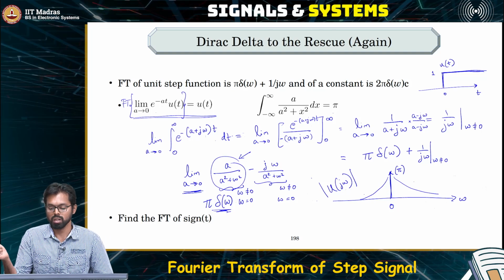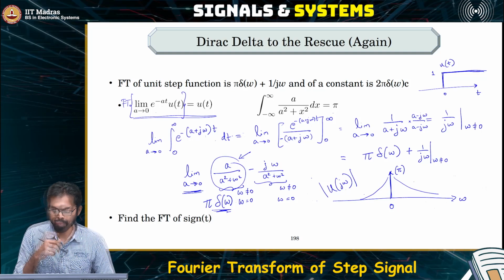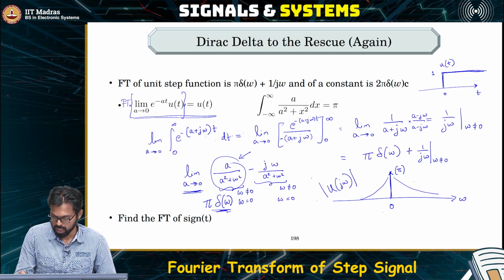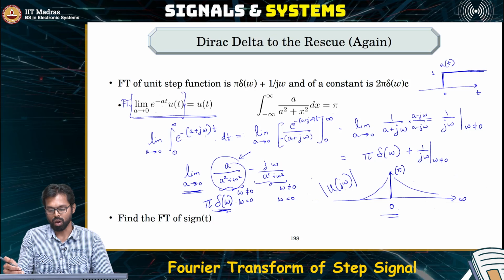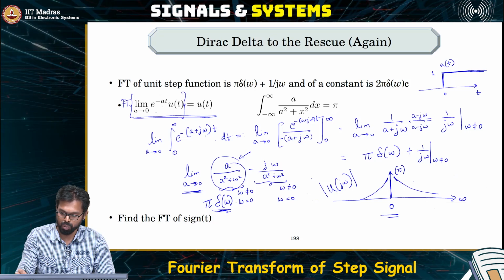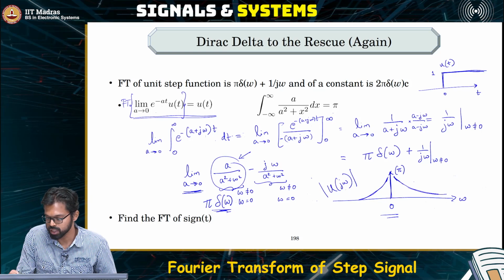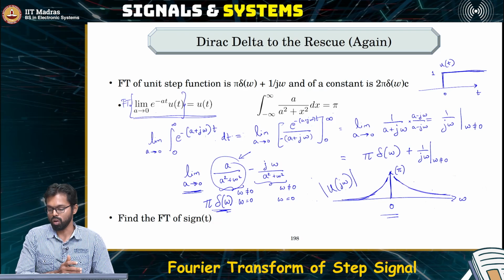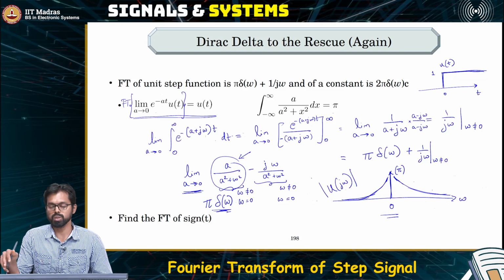So one thing to note is, this looks like a low pass filter. It increases the amplitude of lower frequencies, because the gain, or the frequency response, for lower frequencies is very high, and as frequencies go up, the frequency response is almost closer to 0, which means it attenuates those frequencies.